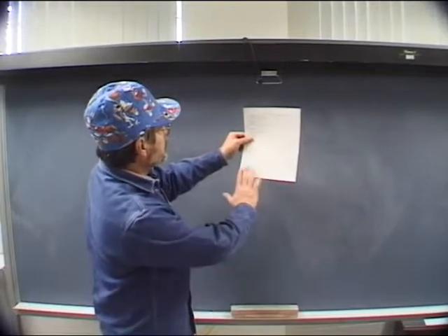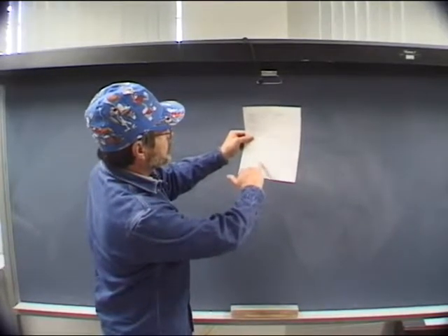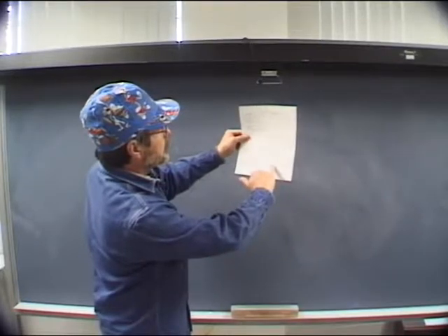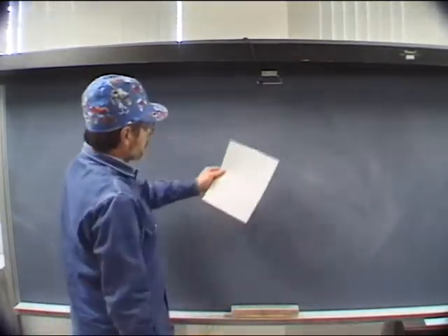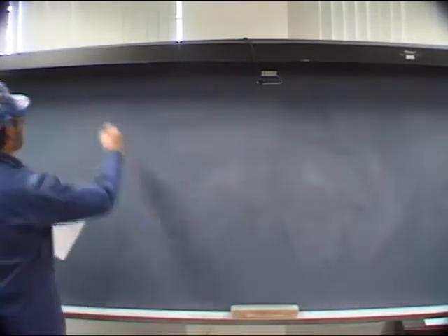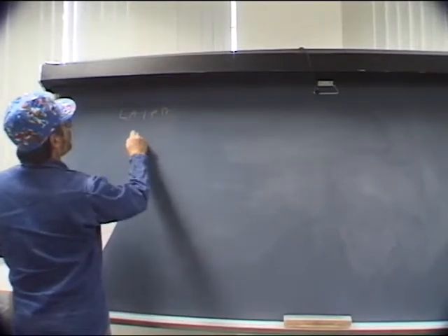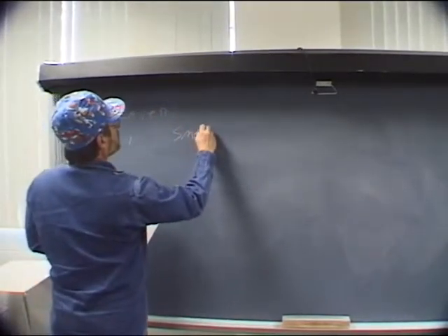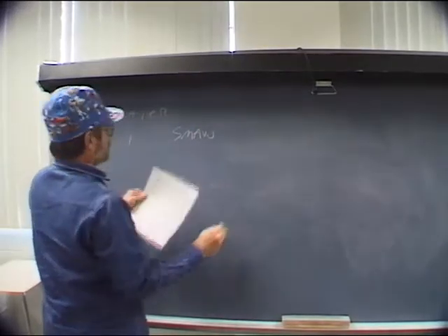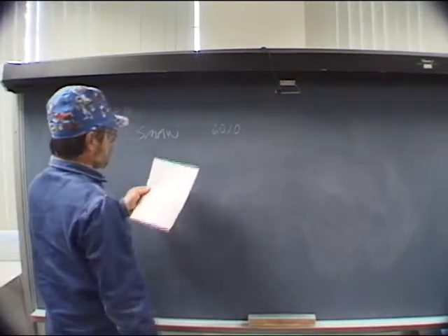Okay, so that brings us down here to this bottom part where it says weld layer, process, filler metal, current, voltage range, travel speed. So now we're going to put individual stuff in here. Where it says weld layers, you're going to go layer by layer. Okay, layer 1. Process, we used shielded metal arc welding. The class was 6010 because this first pass is going to be our root pass.